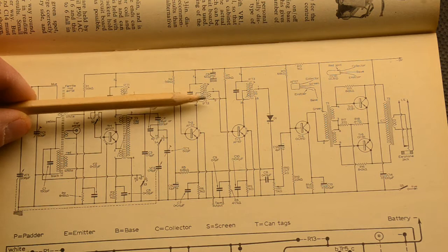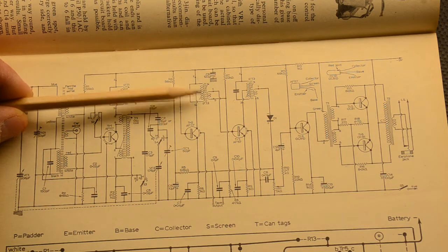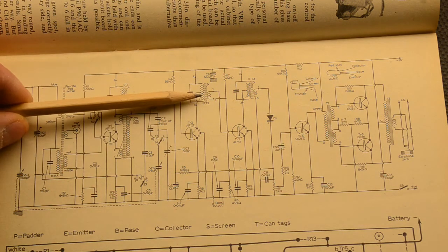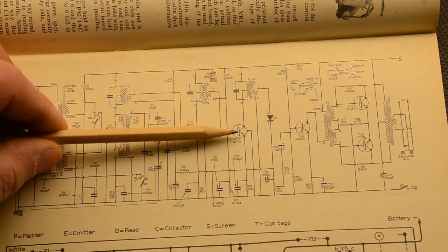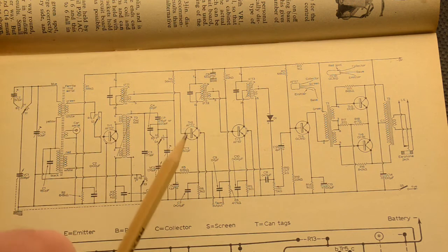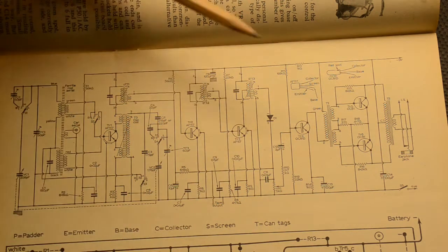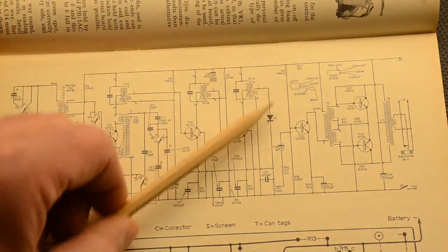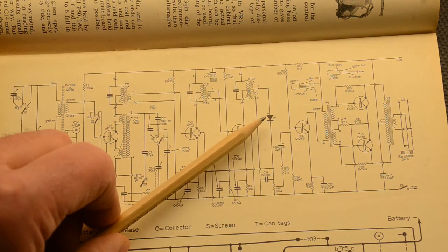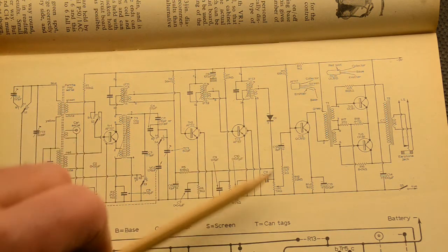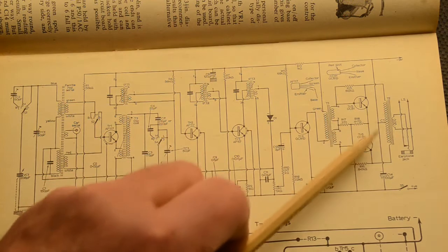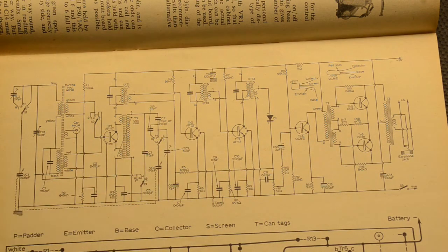goes through a second IFT, intermediate frequency transformer, and it's at the same frequency again, 465k, and it feeds to the last stage, which amplifies it again. So you actually have 2 IF amplifiers here. IFT3, then the output of that goes through the diode for detecting, or demodulation if you like, into the volume control, then off to the 3 transistors that are the audio amplifier.